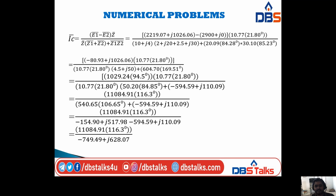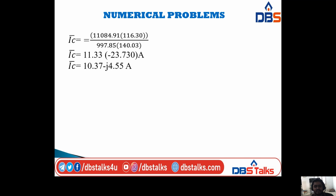After simplifying the denominator we have minus 154.90 plus J517.98 minus 594.59 plus J110.09, that is equal to minus 749.49 plus J628.07. Please convert this into polar form. The denominator is 997.85 at an angle of 140.03. After simplifying, IC bar is equal to 11.33 at an angle of minus 23.73 degrees.